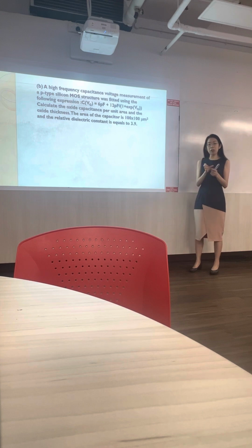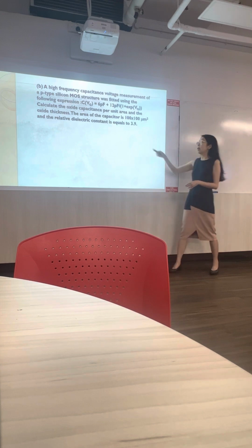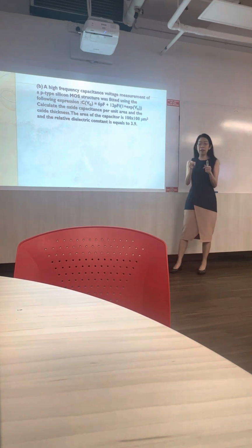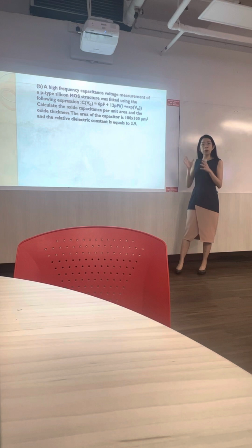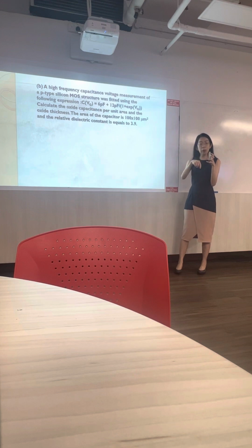The test structure, the device that you are testing, you know the pad size area is 100 by 100 micrometers square. Of course, it's fairly small, your eyes can't see it. There will be a microscope with a probe. You look under the microscope, you put the probe there, then you press the button. That's how it is done.